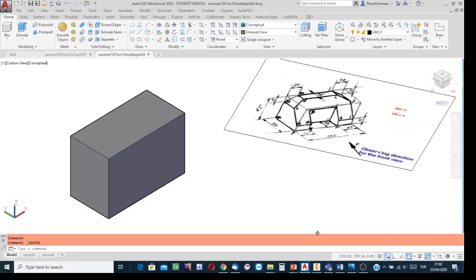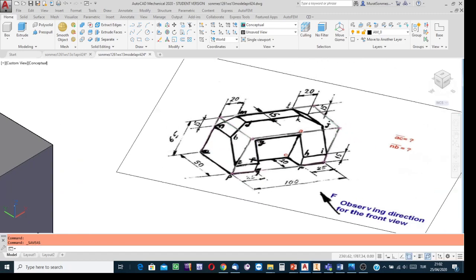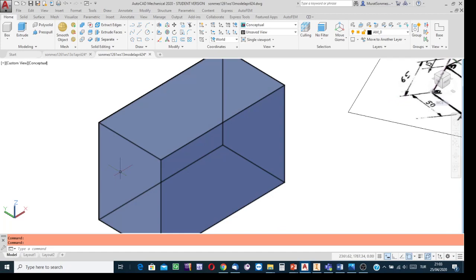Follow my recommendation. Well, I know that this is the left side surface, and the edge of the inclined surface has boundaries E, F, G, A, H, I, J, K, D, B, E. That surface is perpendicular to that left side surface. So on the left side surface, by drawing the edge of the surface and adding the other boundaries, we can have the necessary profile.